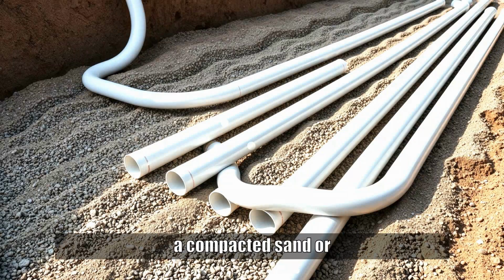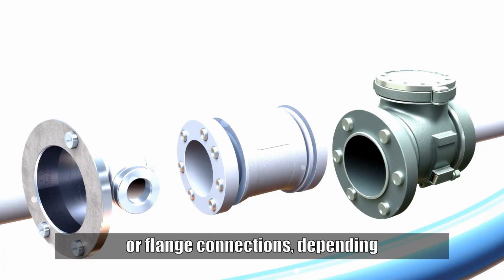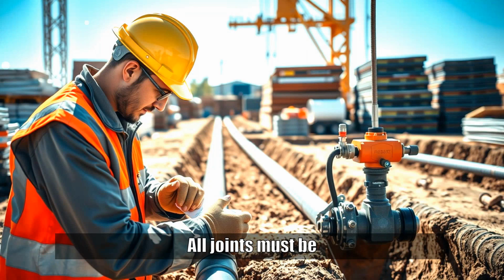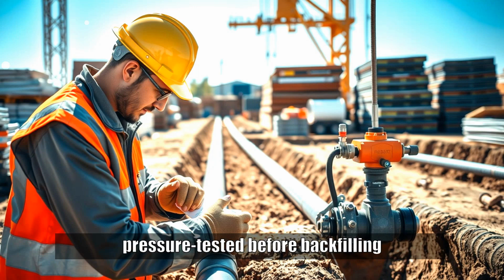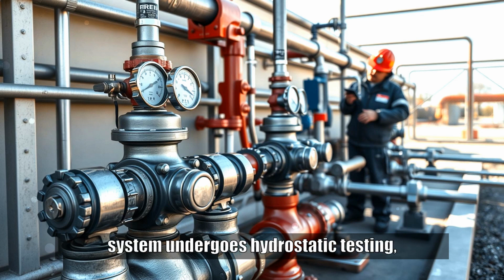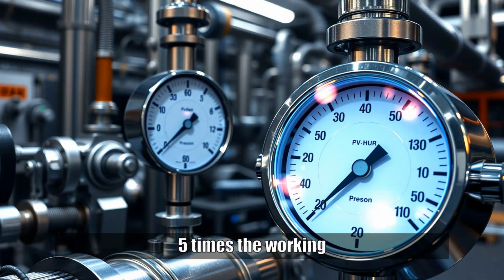Pipes are laid on a compacted sand or gravel bed to prevent damage, with proper alignment and slope. Joints are made using mechanical couplings, solvent welds, or flange connections, depending on material. All joints must be pressure tested before backfilling. Once the hydrants are installed and connected, the system undergoes hydrostatic testing, typically at 1.5 times the working pressure for a duration of 2 hours.